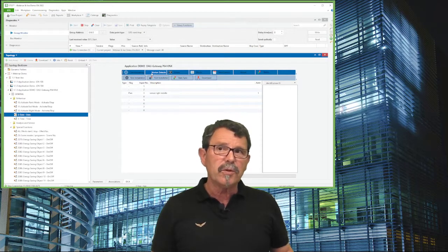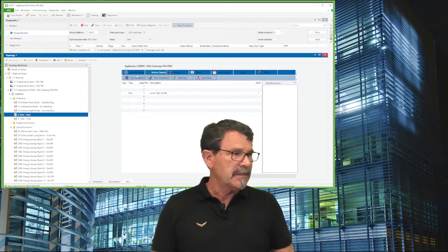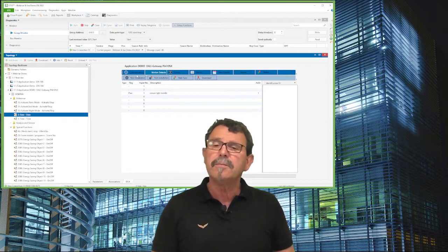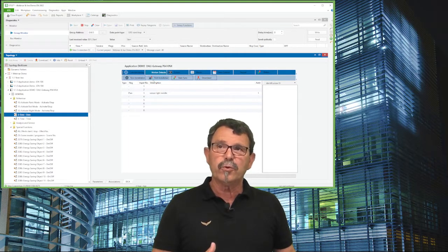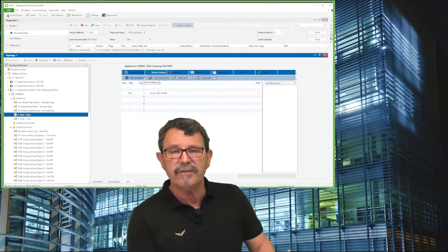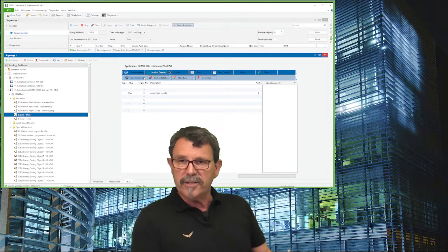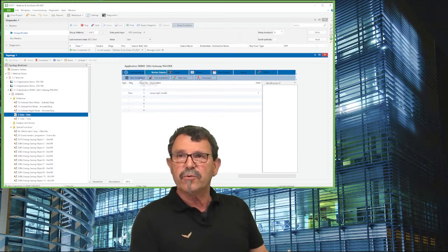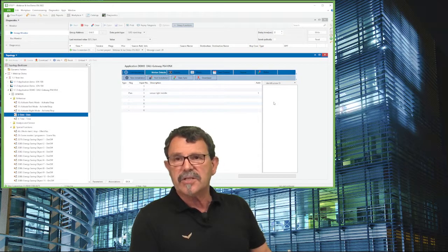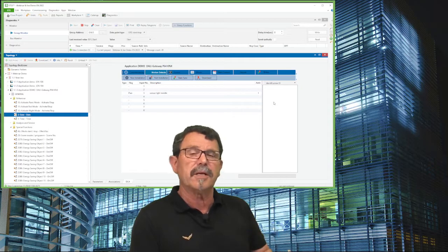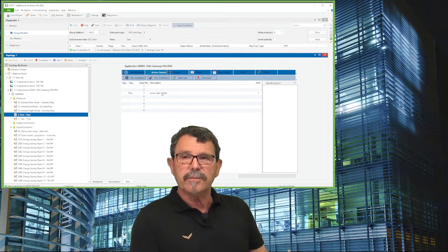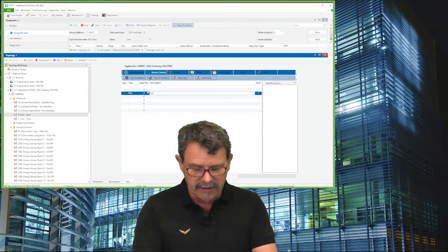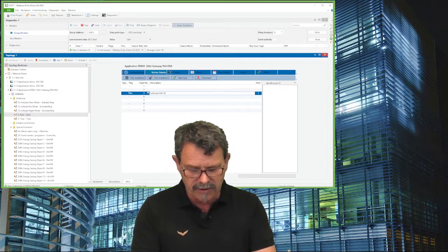When it comes, for instance, to a motion sensor, you want to integrate a DALI 2 motion sensor or presence sensor directly on the DALI side. Then you have to start the installation or the new commissioning when the sensor is wired and applied in a DALI system. Then on this side the sensor shall pop up and be displayed, and then just by drag and drop you put it here in the middle, you name it, and that's it.